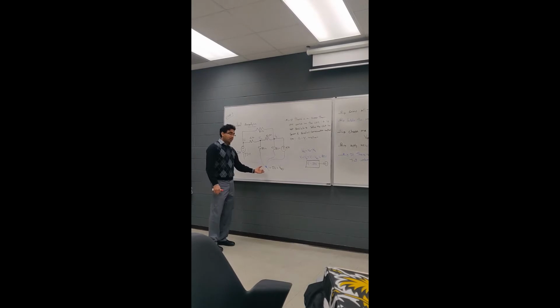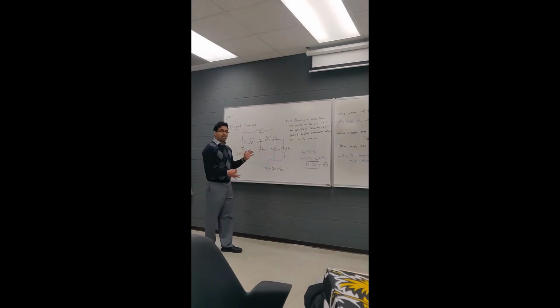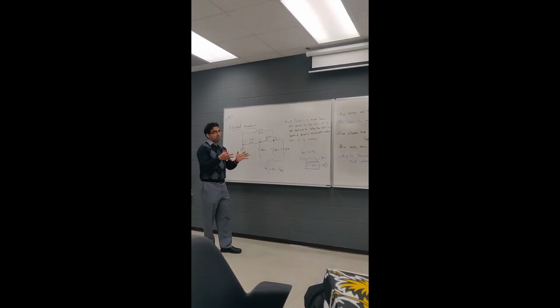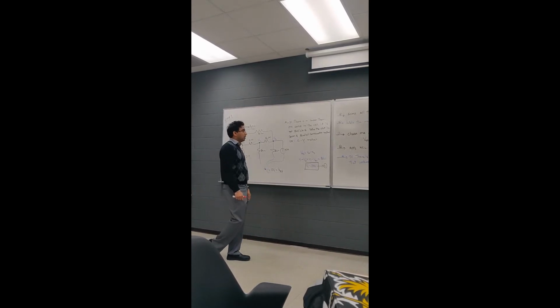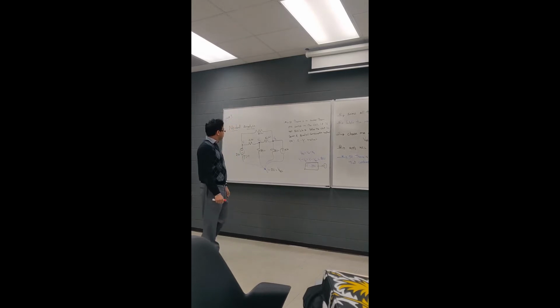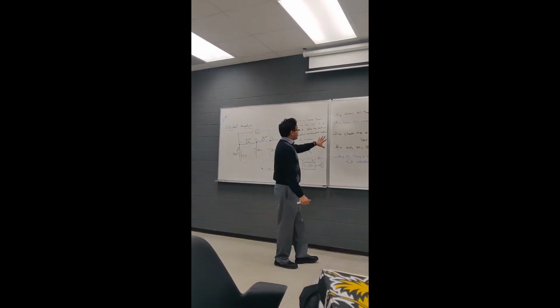Most of the cases, you will end up having more elements connected to the bottom node. So you will end up with a smaller portion of elements in each equation. So I would go with the bottom as the reference node. So that's step 3.